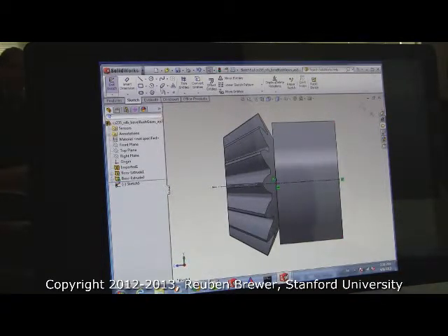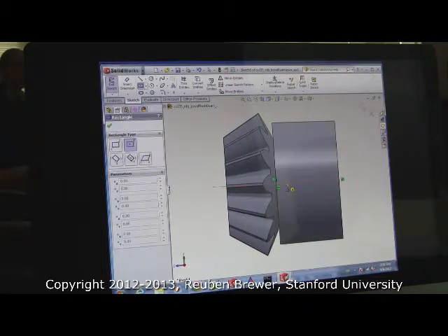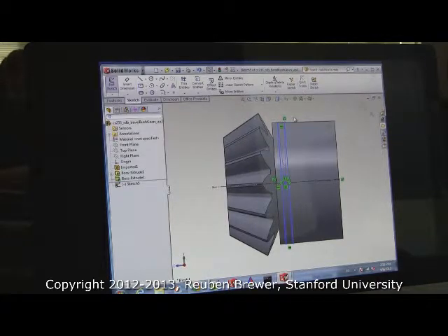Okay? Now up here is a rectangle. There are a bunch of different rectangles. We're going to be using two today. The first is a center rectangle. Click that. Click on the horizontal line about here and drag up, and I want you to let it snap to the edge of the gear right here like this. Go ahead and do that and hit escape. Everybody have a rectangle? So now let's size it.